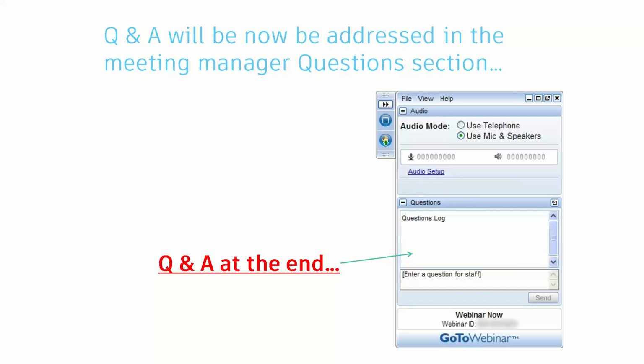Exactly, and everybody needs to take a mental note. When you download or you receive a component from someone, a single component or an assembly, if you open it up in Inventor and it's coming in as a surface and it's coming in with issues, there are multiple reasons why you have those surface issues. For one, Inventor calculates surface extents farther than other CAD packages do. We calculate surface extents and accuracies out to 8 or 10 decimal places, where some of the other products stop at 4 or 5. So we may see errors that they don't.